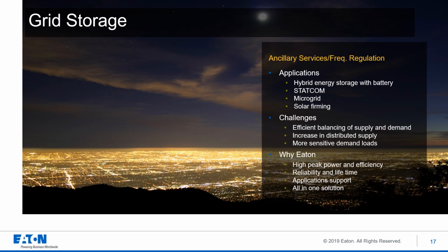The last application I'll talk about is grid storage. This can be true grid energy storage connected to the distribution system or on microgrids. Firming of renewable output was the first use of supercapacitors in this space. The high power, fast charge and discharge of supercapacitors matches well with the variation of solar output as one example. More recently, as we have seen different generating resources entering the grid that have less inertia than traditional turbine generators, there is a need to inject power using STATCOMs and avoid voltage and frequency variations on the grid.